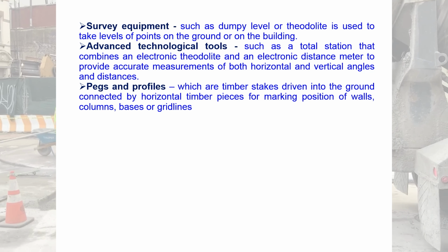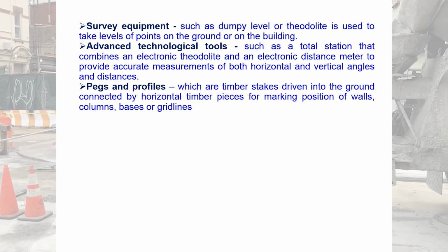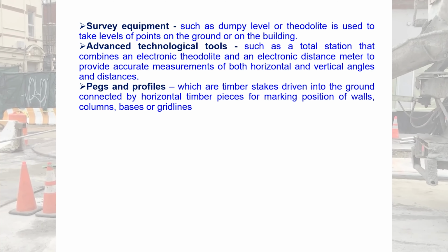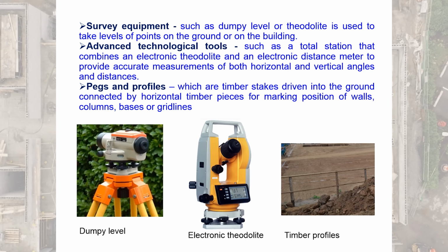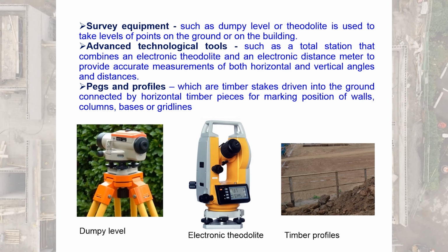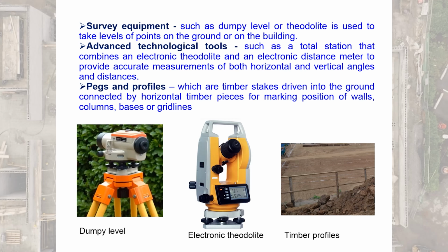Pegs and profiles, which are timber stakes driven into the ground, connected by horizontal timber pieces, are for marking positions of walls, columns, bases, or grid lines.